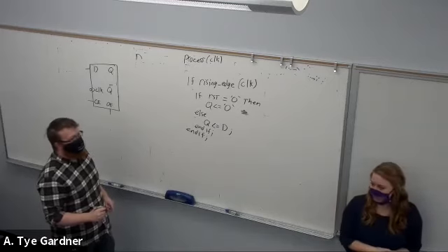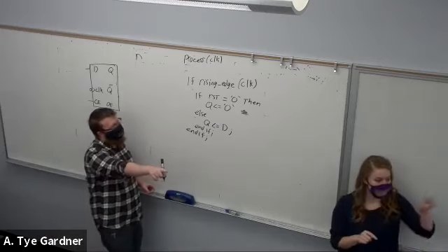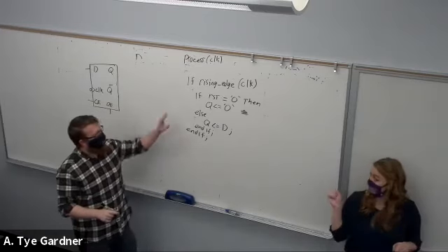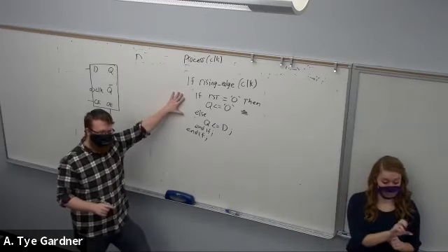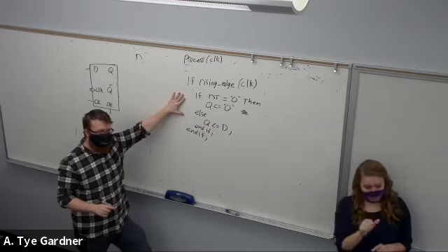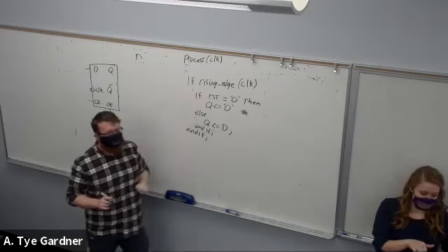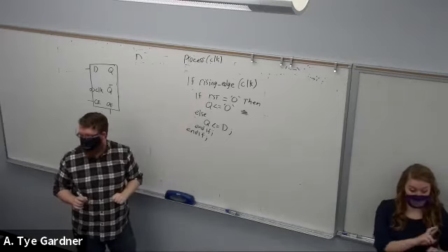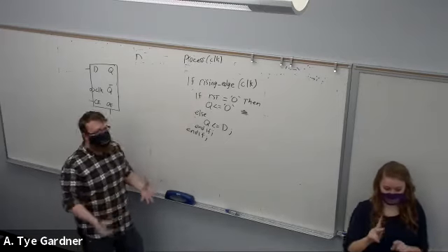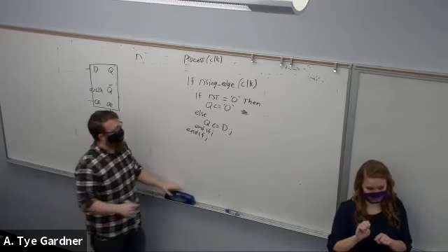In the corner, sorry, I don't know your name. Is this a synchronous or asynchronous reset? Synchronous reset, because it can only reset if rising edge of clock. Let's go ahead and build it into an asynchronous reset.